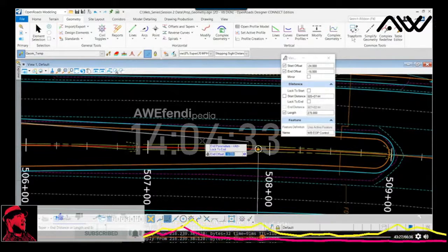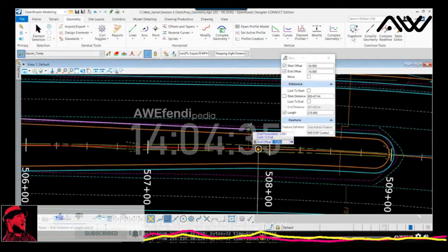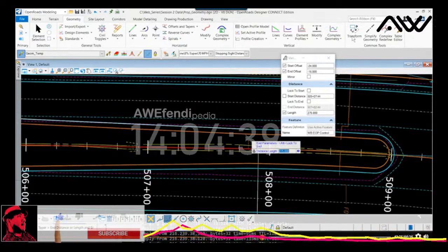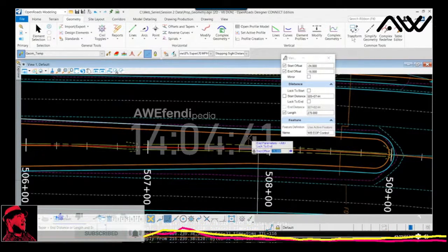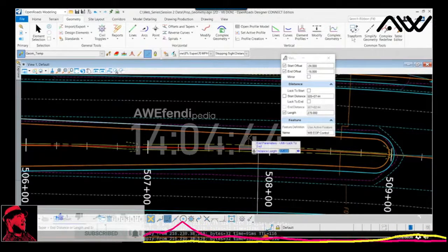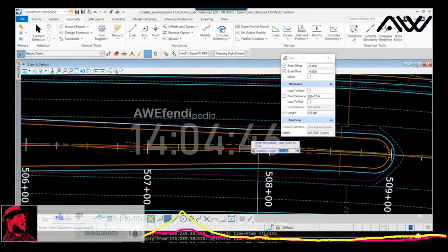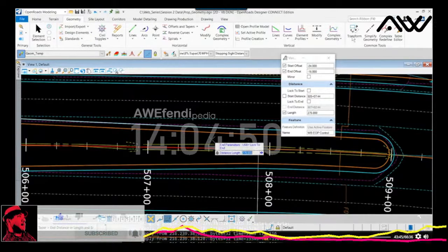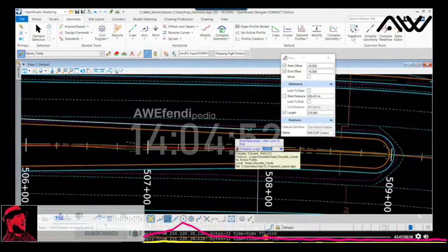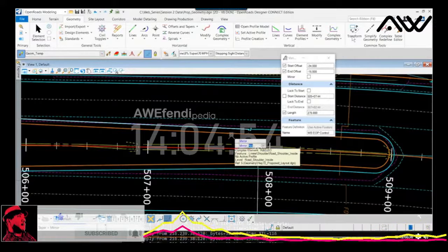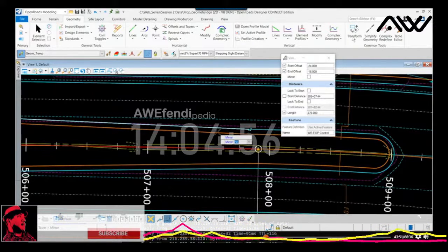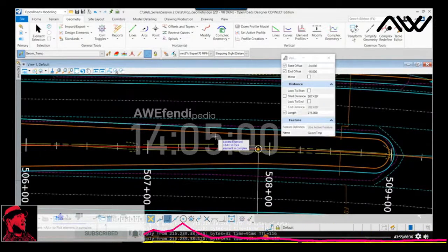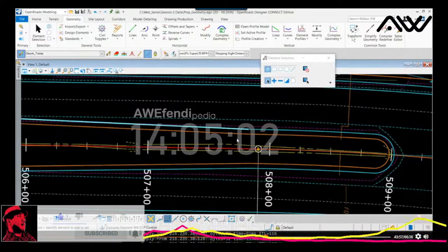So we see now it overlays the graphic. Again, I'll push to the right, and you'll notice I have a couple of data fields here, an additional one. I can put in the set distance for the taper, which I'm going to set at 275 feet, which you see keyed in the field. Then I'll data point to accept it, leave mirroring set to no, meaning I don't want to mirror this to the opposite side of the alignment. And now we have an additional geometry element built.